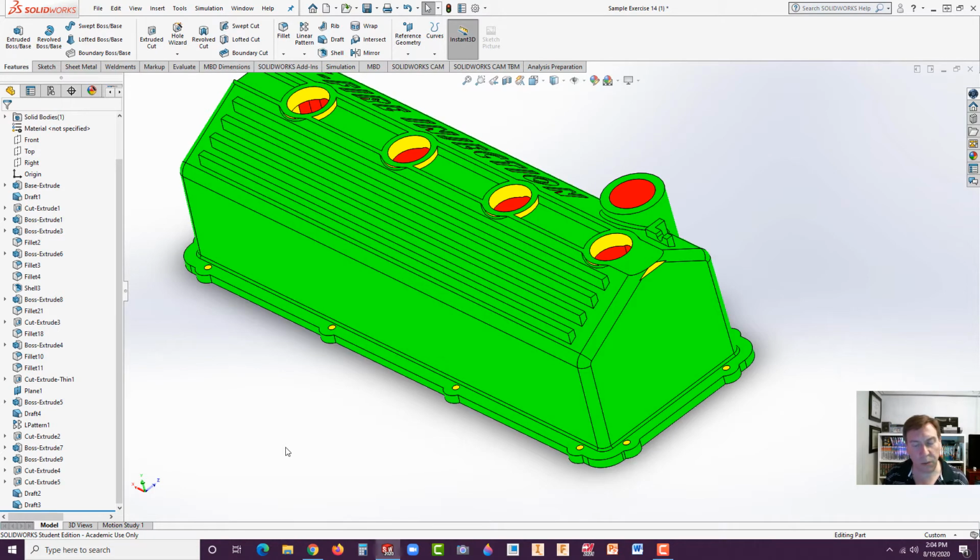So there you can see when you're editing parts, you're dealing with time and when that comes into play. So you might have to bring it back in time, and you could do that using the rollback bar. Drag that up, insert, drag it back down. You could use it just by adding the feature at the bottom and dragging that up and relocating it too. So there's a number of ways we could have addressed this.